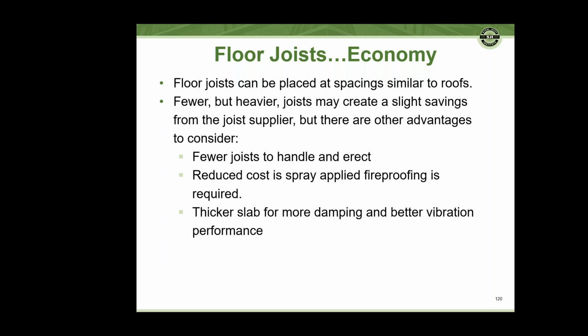If it's an application where there's going to be field applied sprayed fireproofing, those costs certainly go down if there are fewer joists. And if we have joists at larger spacings on a floor and a thicker slab, that just creates a better situation for damping and better vibration performance. It's a little bit counterintuitive because you would think that maybe more joists would make it stiffer, but it's actually the slab that makes a significant contribution, and a thicker slab and joists spaced a little bit farther apart can be advantageous.